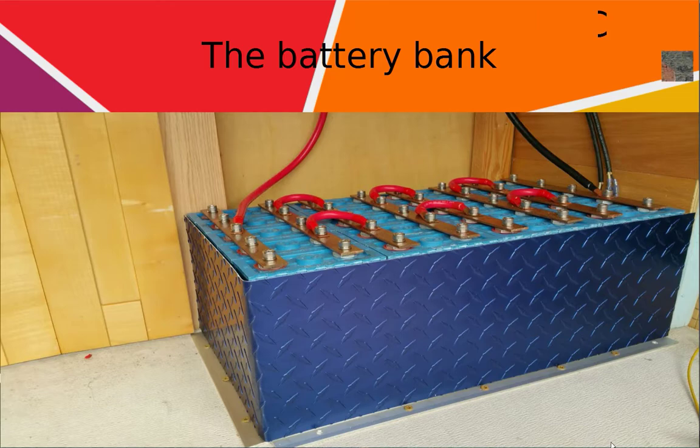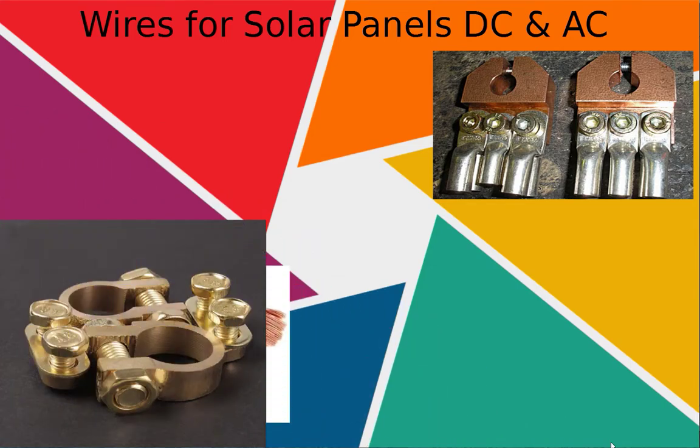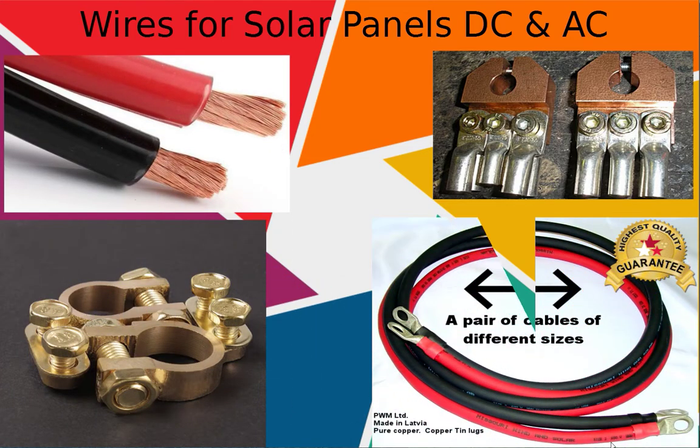Wires for solar panels, DC and AC high voltage output. Choosing the right wire for your solar energy system is critical to its functioning properly and remaining undamaged. If you get this wrong and choose a PV wire too small for your PV system, your battery bank may not charge fully, and as a result your appliances might not work as well or at full power. Thicker PV wire costs more than thinner PV wire because it can handle more amps.